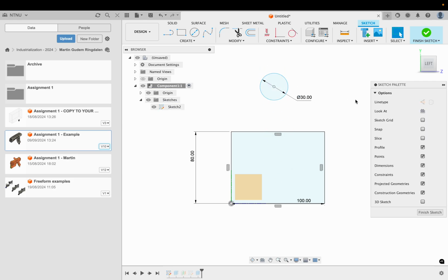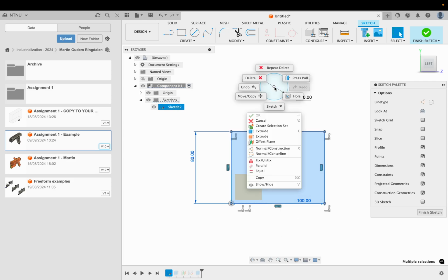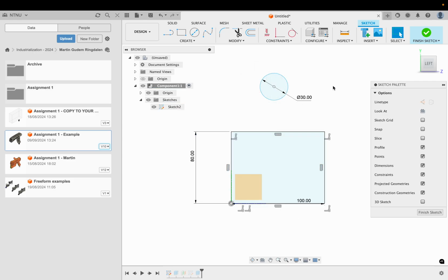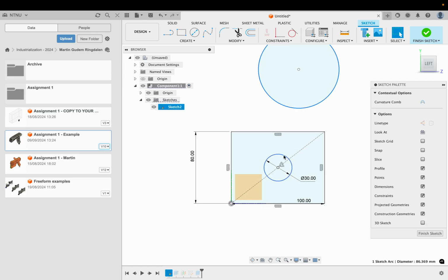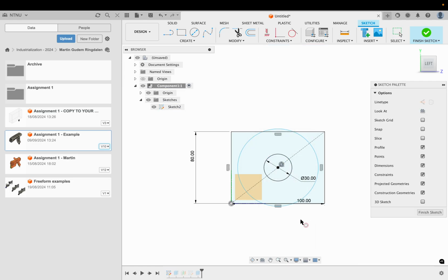Because I can center for sure. I can center circles. Yeah. But I think when you do that, no, I cannot do that because centering is on points. So I can try it though. Let's say we select that and then we select this. It's not letting me. But I could do something else. Let's say I make another circle here. I could say that it's concentric. Yeah. So if that's concentric, that's just going to center them on the shape. But really, that does the same thing as centering the points. But sometimes you will have part of a circle where it makes sense to use concentric anyhow.